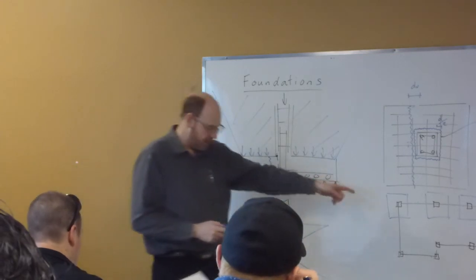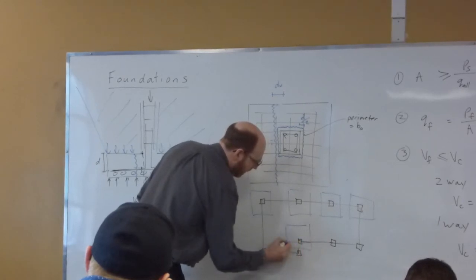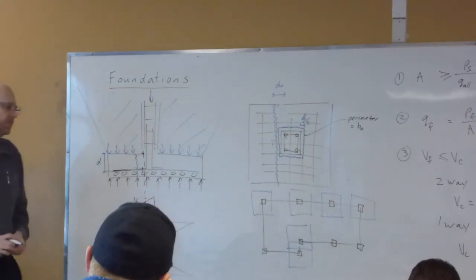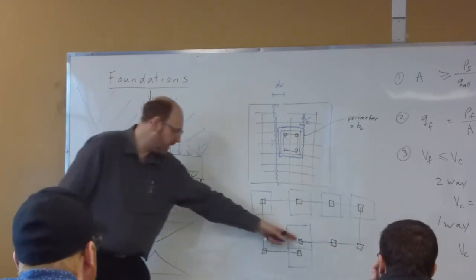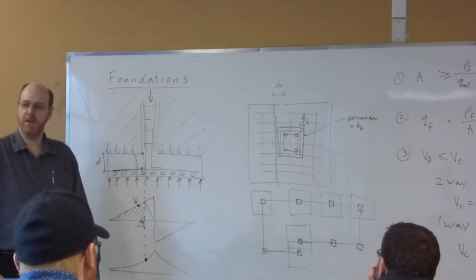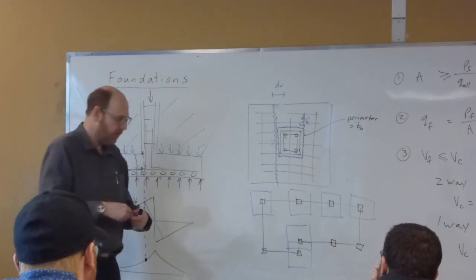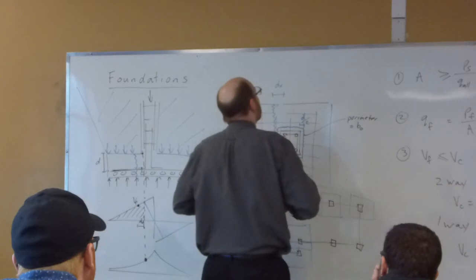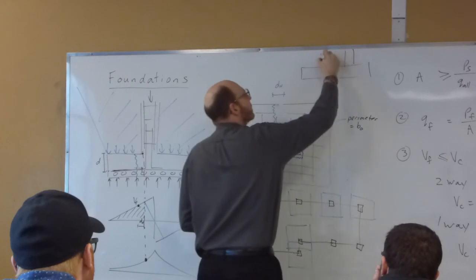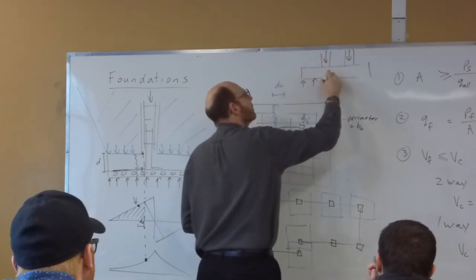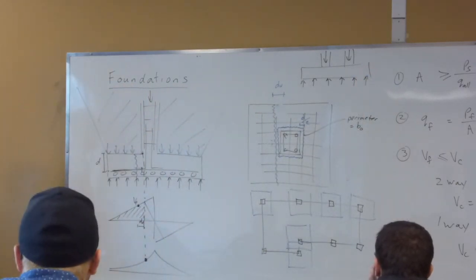Now, as we start putting our footings around here, if I try to put my footing in here, what we're going to find is that they actually overlap. And that's not uncommon to have a scenario where you have two columns that are relatively close together, so you end up with an overlapping scenario. So what we're now doing is analyzing with one big rectangle. So we would put our footing in like this. So we've got load coming out here and like that. So we're now analyzing it with 2 point loads instead of 1 point load.